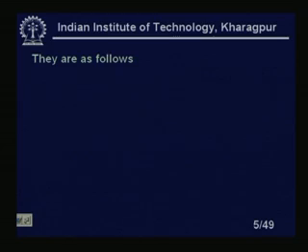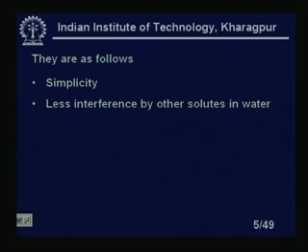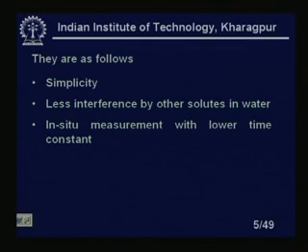They are as follows. What are those? Simplicity. Their design is very simple. Less interference by other solutes in the water. If you have a chemical analysis and want to measure the partial pressure of oxygen or the dissolved oxygen concentration, other solutes will also react with your sample. That will create a problem, and you will not get the exact value of in situ measurement